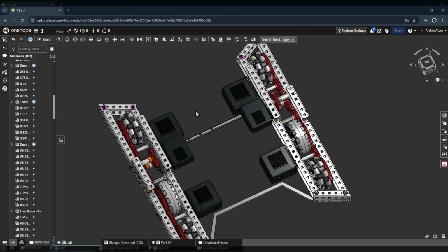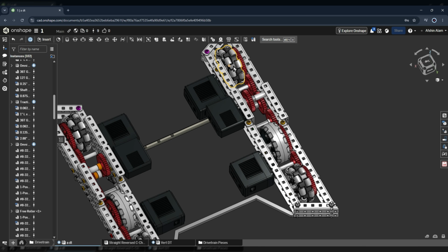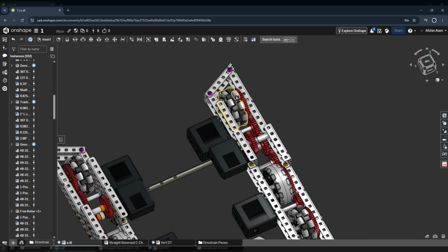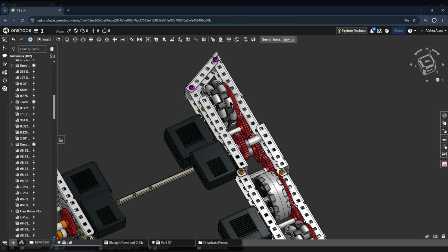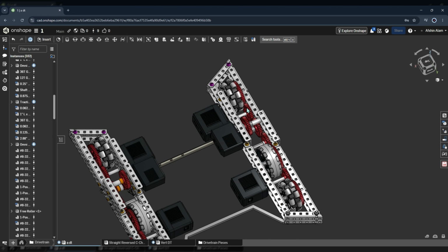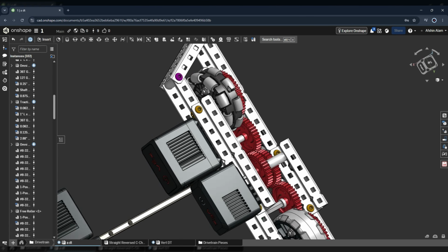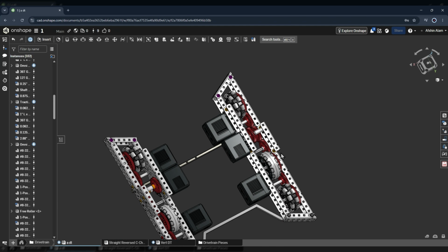For example, when you have a whole drivetrain CAD or a whole robot CAD, you want to have multiple sub-assemblies put together and then have those come back in. Because then, one, when you're working on these little parts, you don't have to worry about loading each of them. And also, if I were to change one of these omnis in that subassembly, you'll change all of them. So it's a lot faster to make edits. That's one real nice thing.